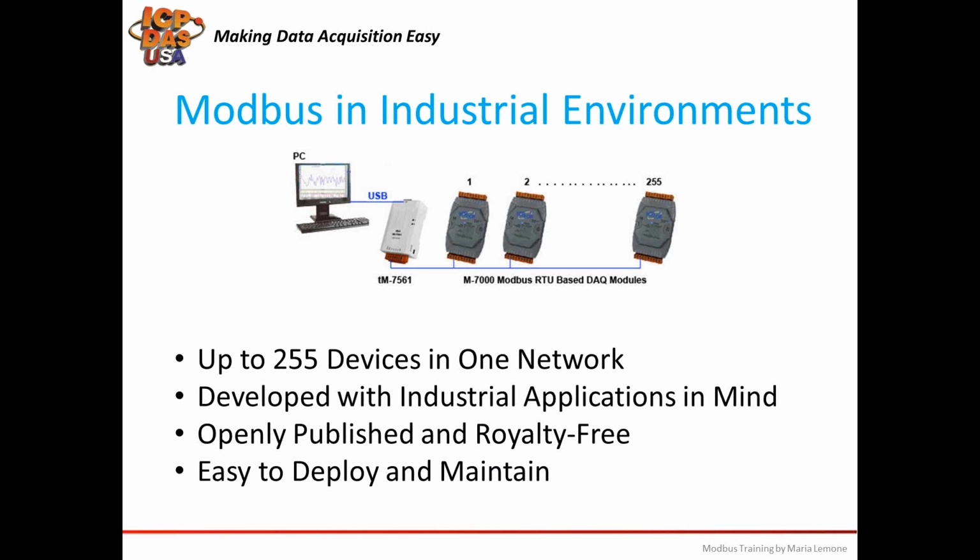Modbus RTU allows for communication between up to 255 devices in one network. For example, a computer can collect temperature and humidity levels from Modbus RTU-based devices in many different areas in a building or manufacturing plant. Modbus is often used to connect supervisory computers with RTU remote terminal units in SCADA supervisory control and data acquisition systems, so you can see the status of the equipment on a PC. It's also used in applications like energy management, machines, remote monitoring systems, wastewater processing systems, and building automation systems.